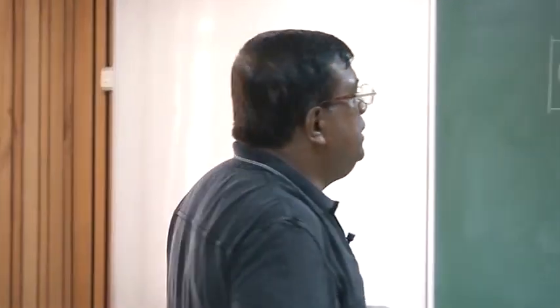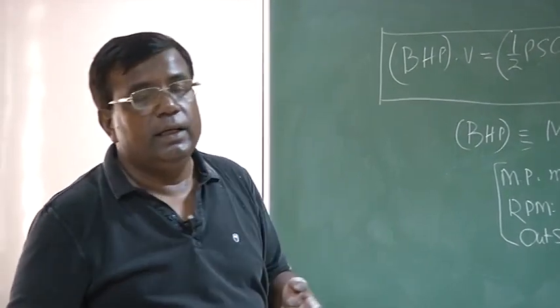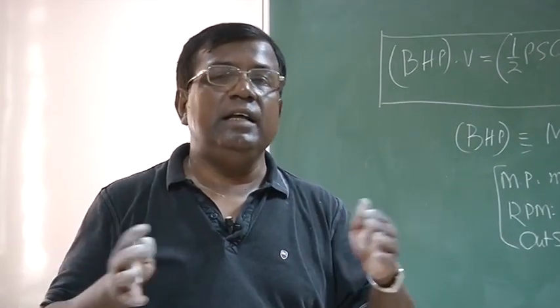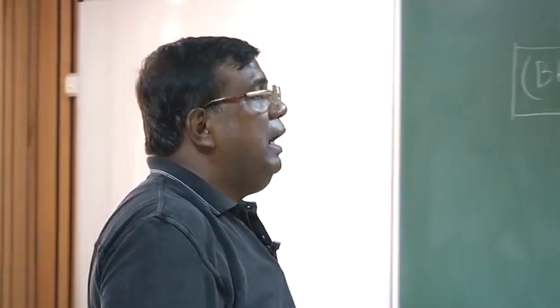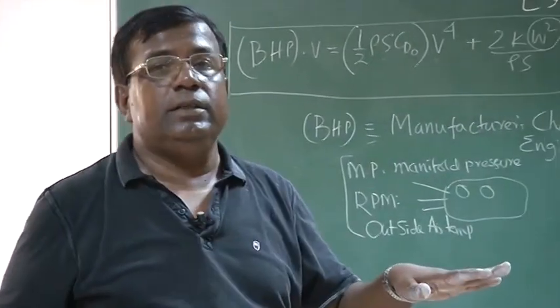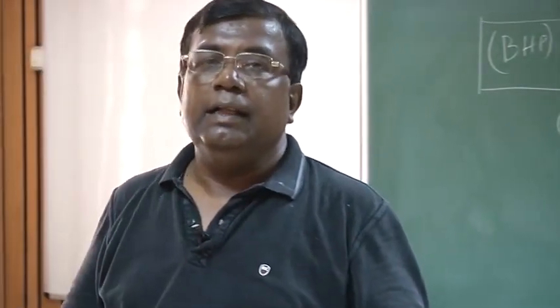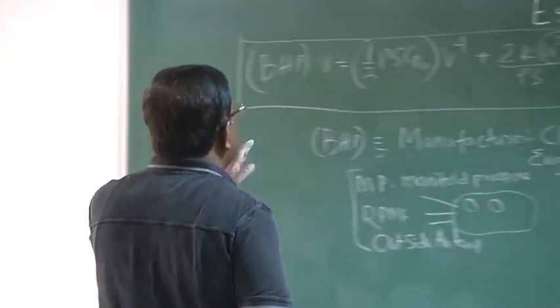The best way is, when I do an experiment, I find out how much time has elapsed, and from there, I use the fuel consumption chart to see how much fuel is consumed for that time and deduct that from the weight. This is one way. Second approach, when I land, I again weigh the machine with all the passengers and then take the average weight. And you'll find they will not be very far off. So this is how I get this information.